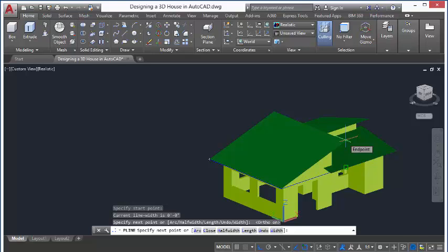If the first point starts with zero value in the Z direction, all the other subsequent points will vary in the X and Y direction, but not in the Z direction. By that I mean, if you start a polyline with the starting point at 0 X-axis, 0 Y-axis, and 0 Z-axis, then when you move to the next point and want to change the Z value, the polyline command cannot allow you.